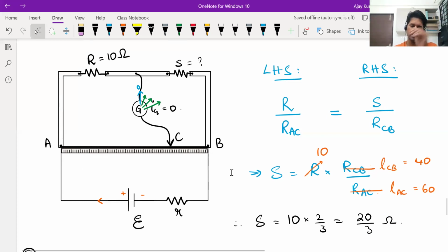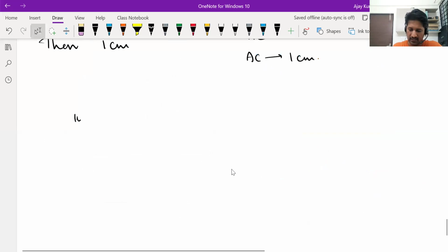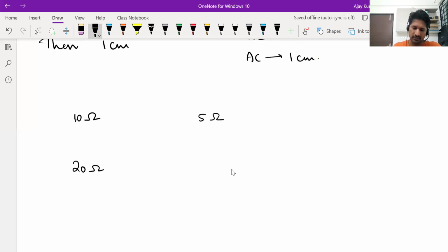Okay, so what I'm telling you is, suppose the resistors on the left hand side are like this: 10 ohm, 20 ohm, and right side the resistors take a slightly higher resistance, say 15 ohm and 30 ohm. If it is like this, it's balanced. The Wheatstone bridge is balanced, then you won't see any current in the galvanometer in between.